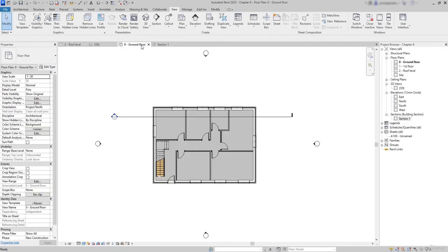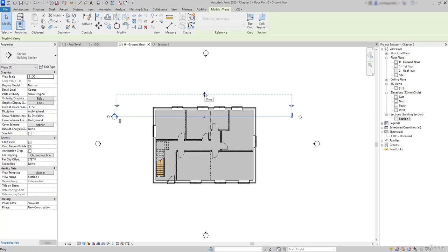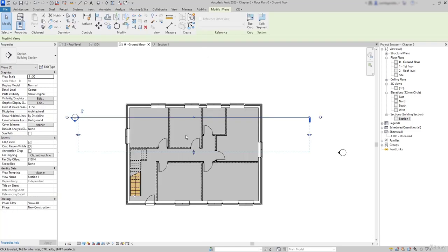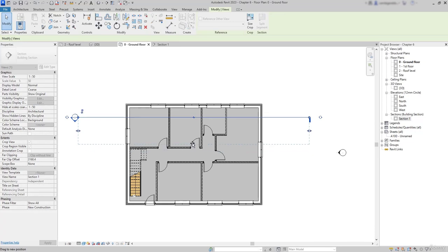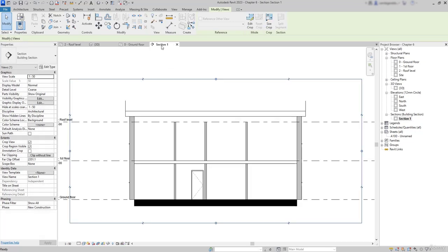Okay, we are going to learn how we can edit this. In this arrow, I can switch the direction of the point of view. And this time you can see it's facing towards the door. If I move the area in a way that I leave the doors outside, they will not show in the drawing, only the door that was inside.